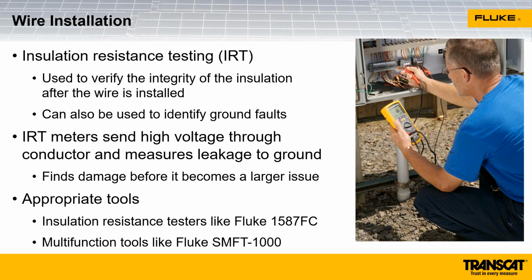There's a couple different tools you can use to do this test. The Fluke 1587FC insulation multimeter can do this test. We also have the SMFT 1000, which is the solar multifunction tool, which has insulation resistance testing built into it as well. And the SMFT is a little different than our standard insulation testers. The standard testers aren't designed to work with circuits that have voltage present.